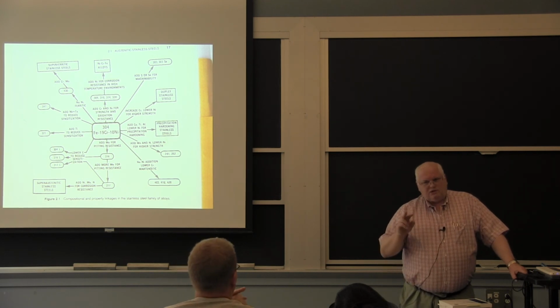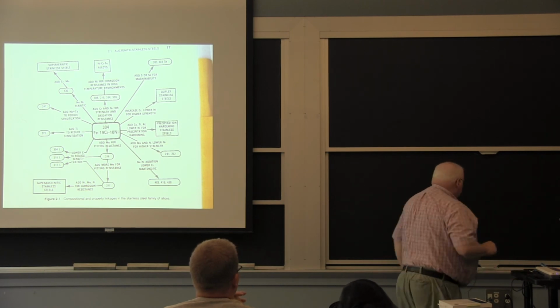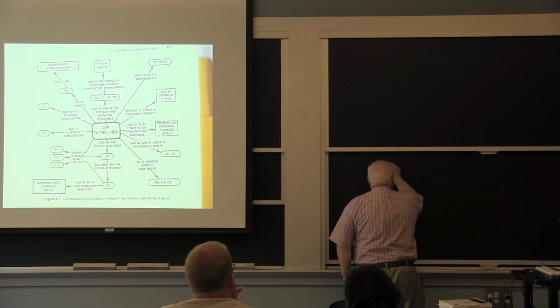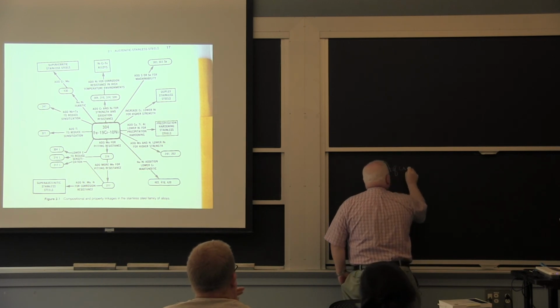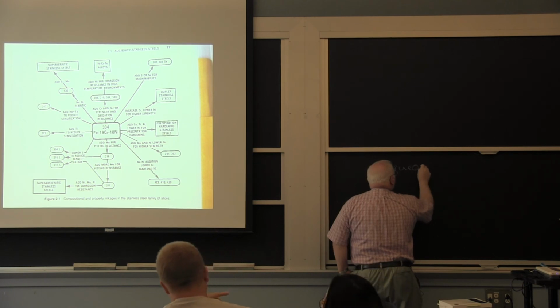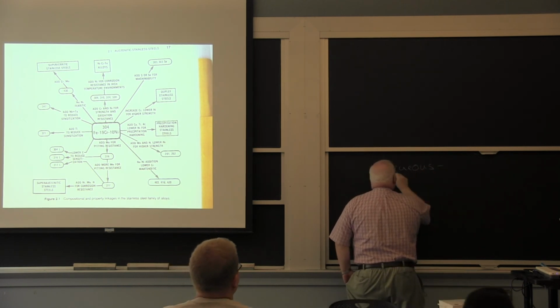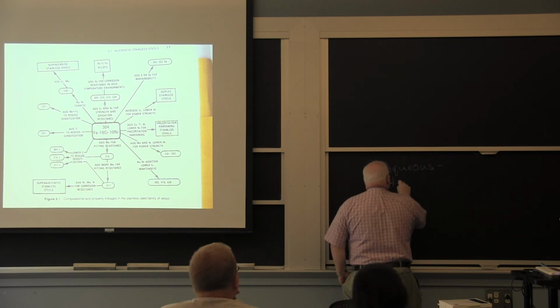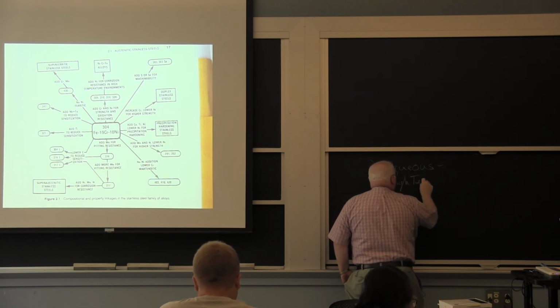So in any case, you tend to use stainless steels in two types of environments. One is an aqueous system, where you need water corrosion resistance in some sort of water. And the second one is high temperature oxidation.